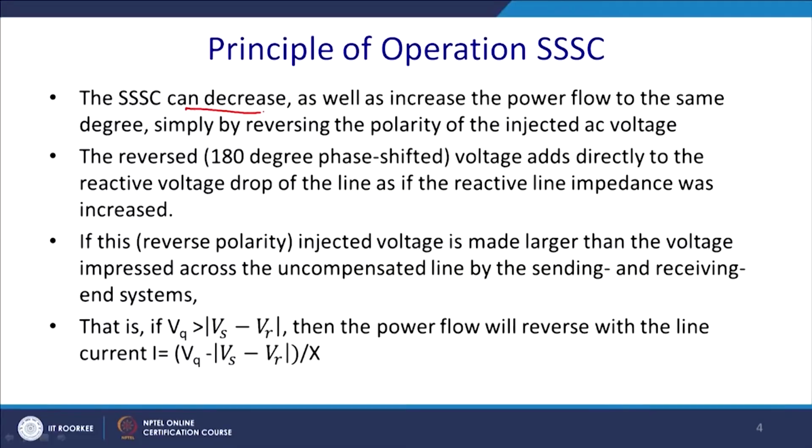So, what is the principle of operation of the SSC? The SSC can decrease, this is one of the best features of it, as well as increase the power flow to the same degree by simply reversing the polarity of the injected AC voltage. So, it can inject plus VQ or it can inject minus VQ.